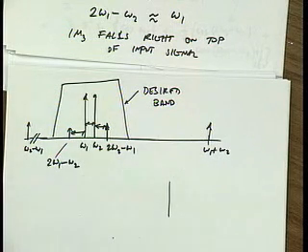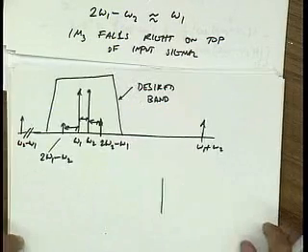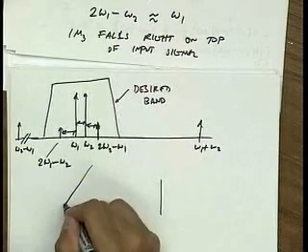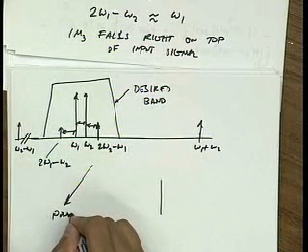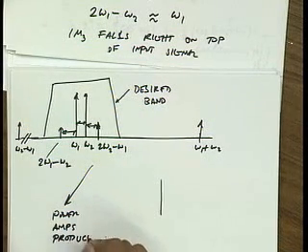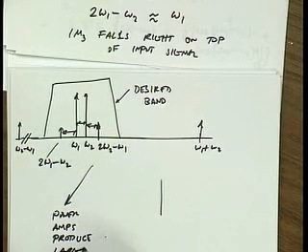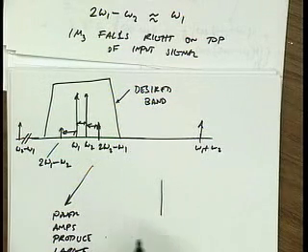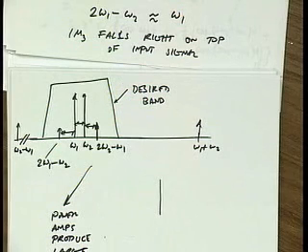Okay, question? Yeah, but here we don't have the problem that the signals causing the intermodulation are much stronger or can be much stronger than the signal itself. That's a good point. That's a very good point. Now there's two scenarios where this still does matter. One is in power amplifiers, because they produce large signals. So power amplifier will self-interfere. In other words, you put in one spectrum and out comes another spectrum that has components that weren't in the original spectrum.